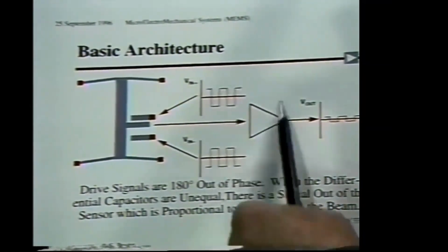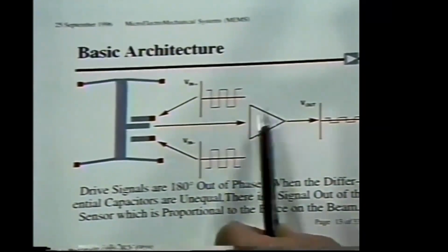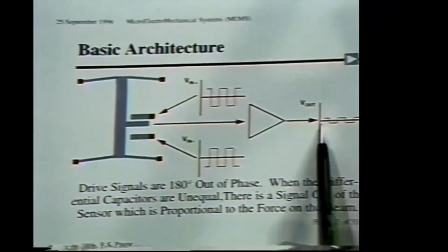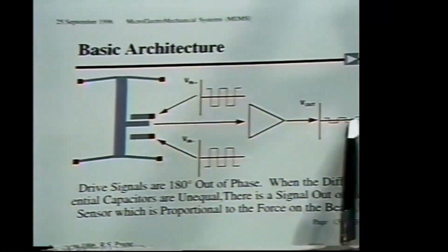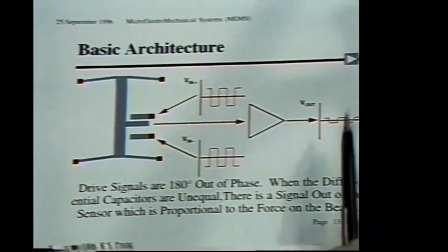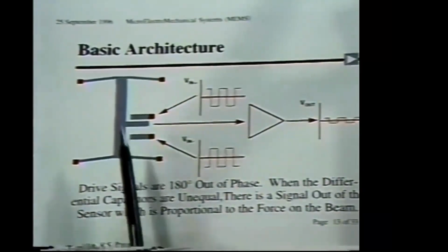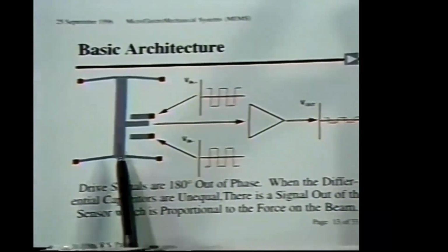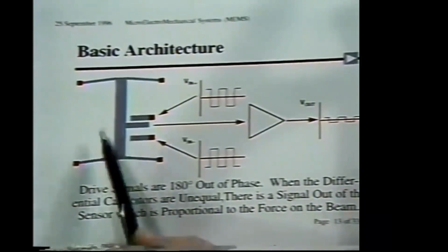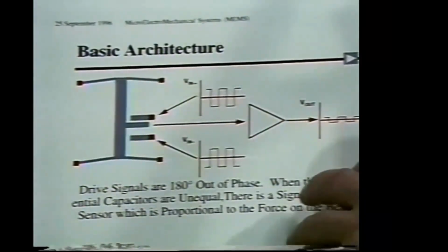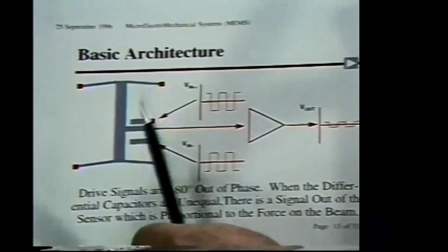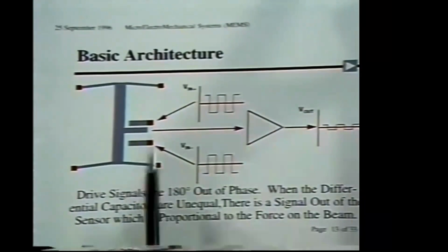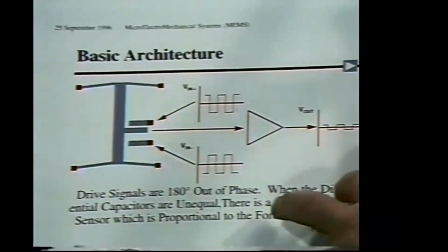Those signals are then demodulated and amplified somewhat, and the phase of the larger capacitor comes out, and the amplitude, due to the very small displacements, is linear in displacement. So this is really a displacement transducer, where a proof mass is displaced against a spring and detected electronically. It's very, very sensitive. The displacement transduction of the airbag sensor is under an angstrom. It's about a half an angstrom that can be sensed. It's the equivalent displacement noise within the device.